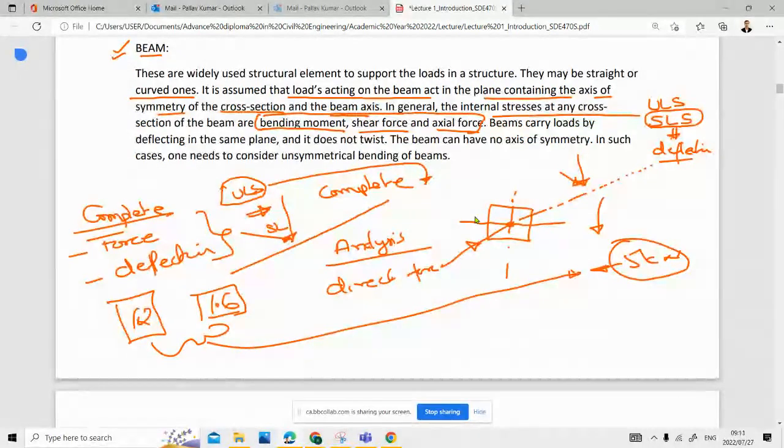Yes, sir. Perfect. And whenever we call SLS condition and you are doing a deflection check in your analysis, that deflection check already incorporates your dead load, 1 times DL and 1.1 times DL, and 1 times imposed load IL. So the load you are taking in your SLS condition in the analysis includes these things, right?